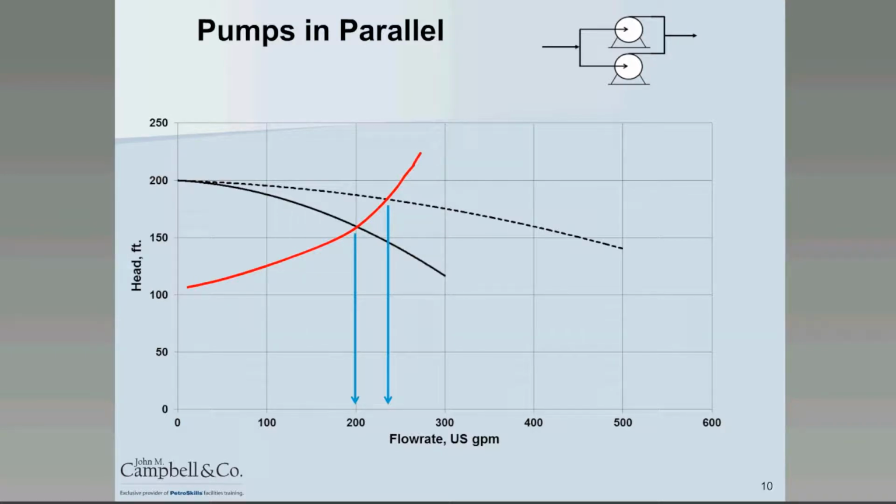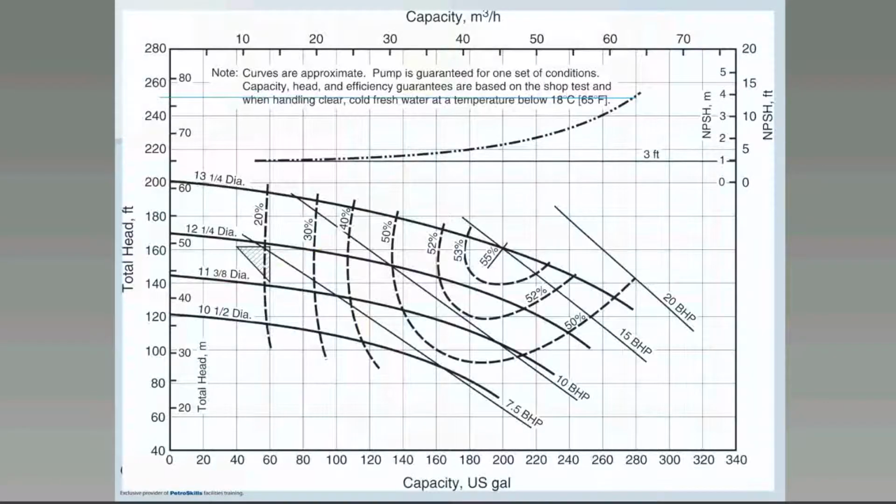People think that, oh, if I start another pump, I'm just going to move twice as much flow rate. And unless there is a strong understanding of the system curve, can that actually be determined? And now we need to pass that information on to the actual pump curve, which is a very important part in this process of understanding what's happening.